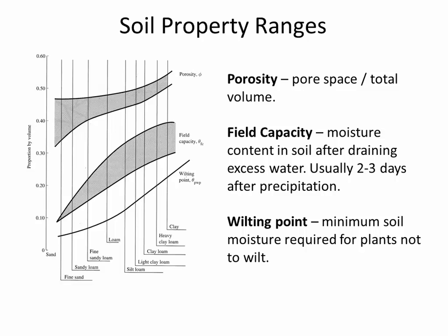And then the other thing is the wilting point. The wilting point looks at how easily plants can take the moisture out of soil. And so what it's showing is that plants can still take water out of sand when the moisture content is as low as 5%. But it's much more difficult for plants to take moisture out of clay.